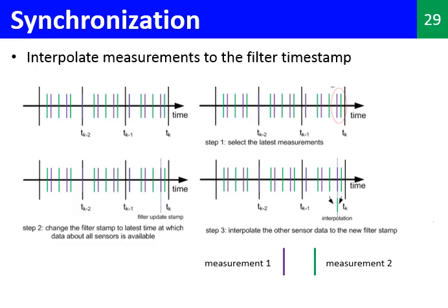Let's say we have a timer that gets triggered at the frequency we want to run the Kalman filter. For example, suppose our Kalman filter gets triggered at 10 Hz. In these figures, the time instances marked in black, t_k minus 2, t_k minus 1, and t_k, are those instances where the Kalman filter gets triggered.